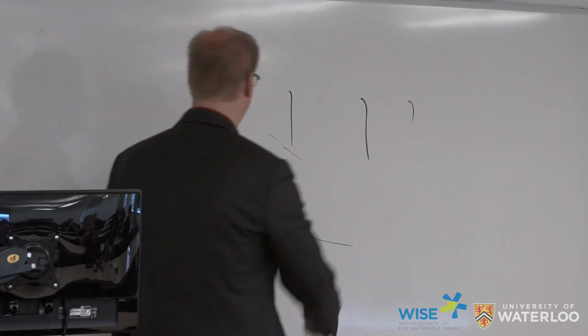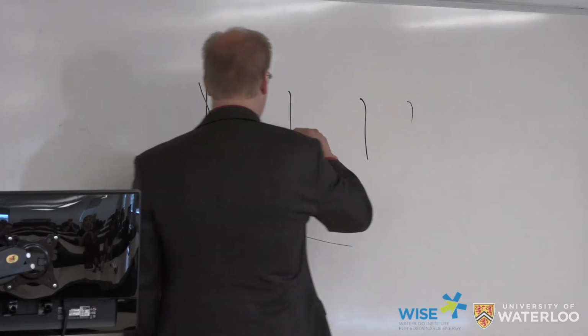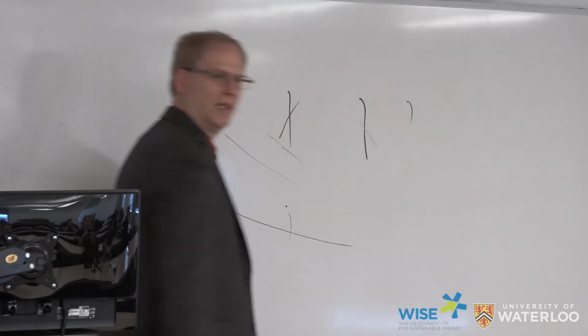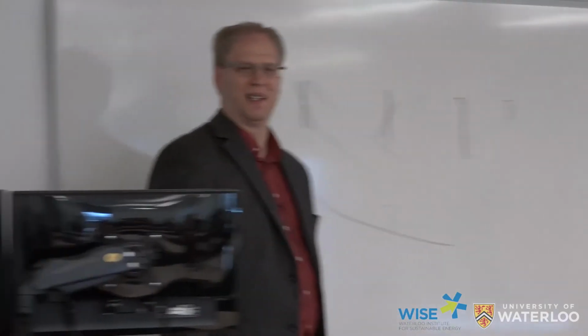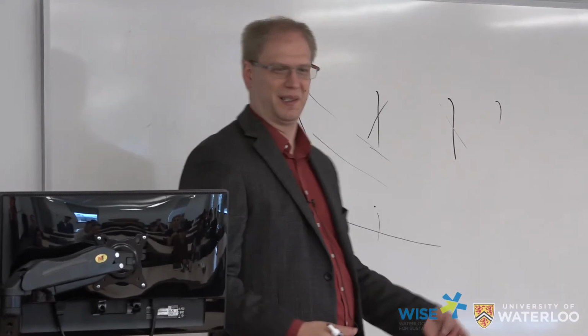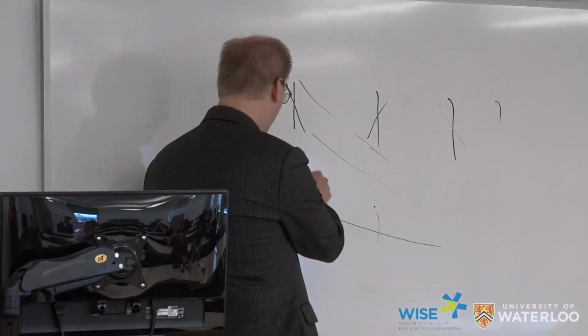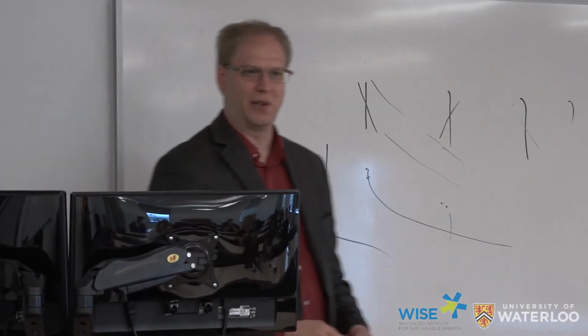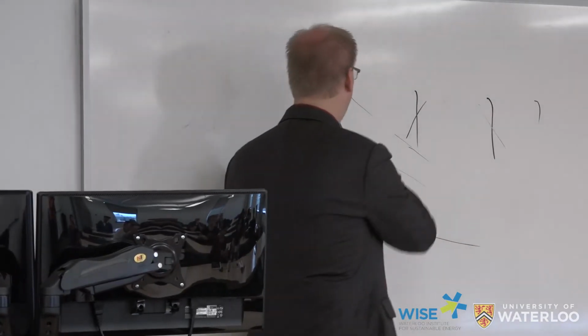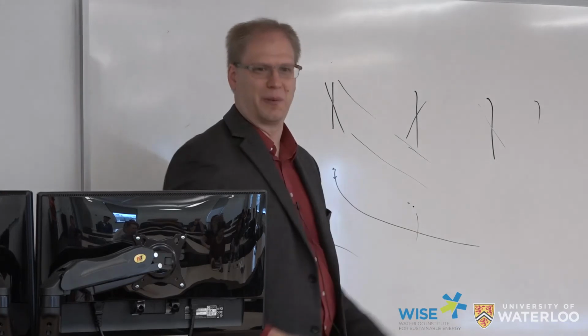And so what they're effectively doing is they're staggering. So this one's this way, this one's this way, this one's this way, and the wakes are up, down, and effectively missing the turbines, and so you're not getting that power on any turbine, but overall it's quite a bit of a boost over the other. And it's both the deficit itself as well as the speed up effect.